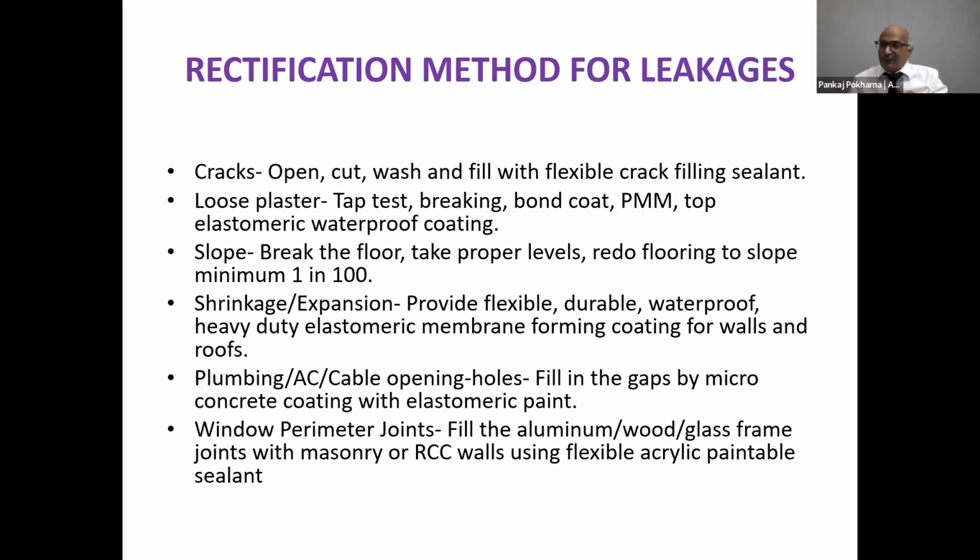If it is not stagnant, then also while you clean the terrace, you will find certain cracks which are visible and certain cracks which are not visible, but when you wash, they become visible to you. Then you have to do the crack treatment. So check for cracks while washing. During washing, you will find hidden cracks also. If the cracks are there, then you have to treat those cracks.